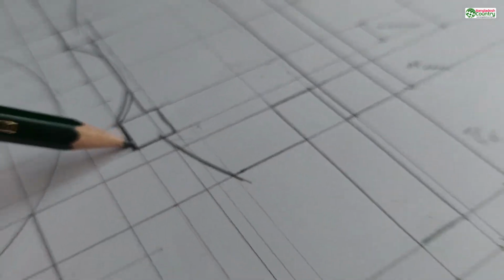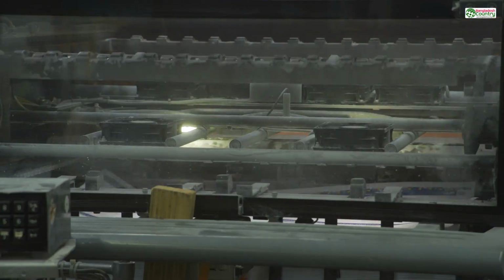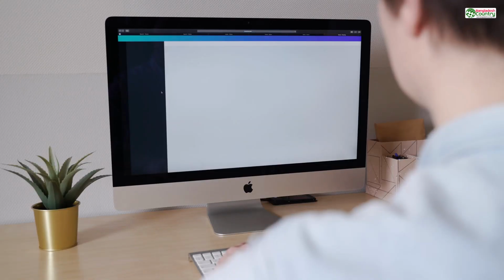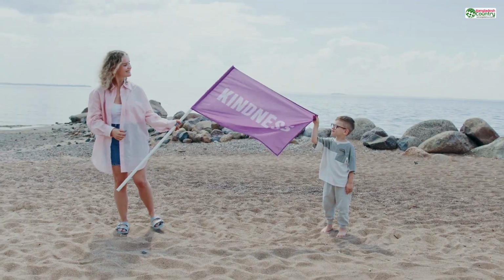Every 3D printing technology has a physical limit, a point where a feature is just too thin to exist in the real world. For a standard desktop FDM printer, the kind that lays down melted plastic like a tiny hot glue gun, a thin wall is like trying to draw a line with a single wobbly strand of hot spaghetti. It will sag, it will be weak, and it might not even stick to the layer below it.